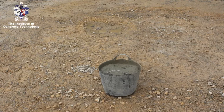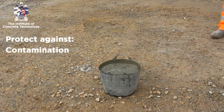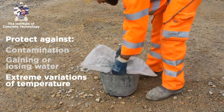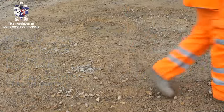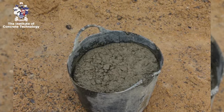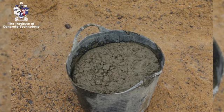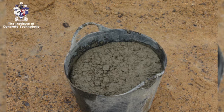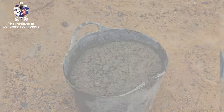At all stages of sampling, transport and handling, the fresh concrete samples must be protected against contamination, gaining or losing water, and extreme variations of temperature. The properties of fresh concrete can change with time after mixing, depending upon the environmental conditions. This should be taken into account in deciding the time when tests are carried out or specimens made.